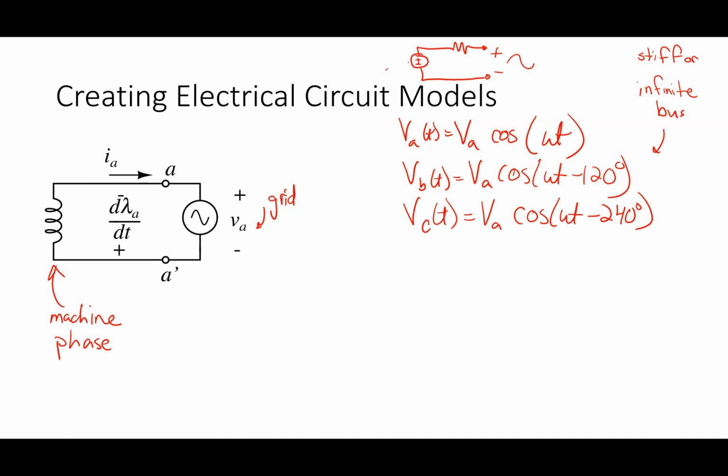Because if this is an ideal voltage source that itself never changes, and this resistance is 0, then fine. Or maybe I should think of it this way. If this resistance was not 0, and there's a current going through here, then depending on that current, the voltage I would see at the terminals would get smaller, right? Like at that outlet right there, if I've got a current coming out of it, the voltage you would see at that outlet would get a little bit smaller.